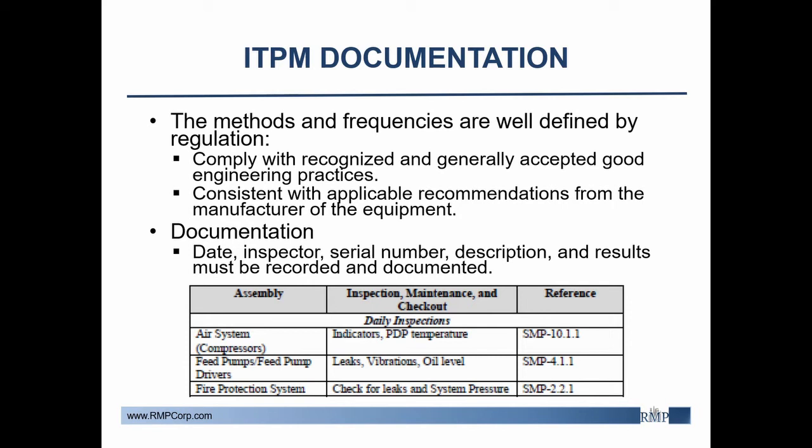The standard also states that the owner or operator of a facility with a process subject to CAPP shall document inspections and tests as they are performed on the equipment, including without limitation, documentation of the date of inspection test, the name of person who performed the inspection or test, the serial number or other identifier of the equipment on which the inspection test was performed, and the results of the inspection test. This can lead to complexity as the process grows.